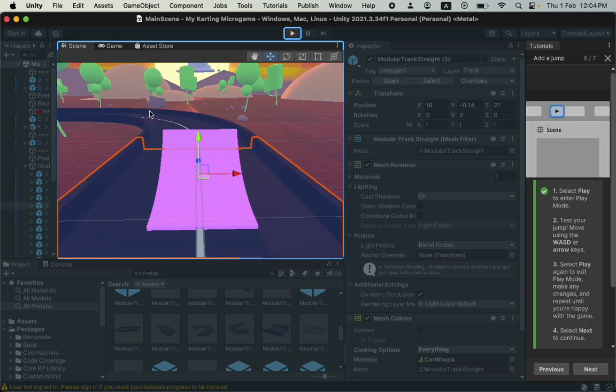Actually, that is not correct. The scene will be wherever it is. Your camera will rotate. Imagine your camera is placed on a sphere, and you want your camera to move. The scene is at the center, your camera is on the sphere. Now you want the camera to move. In that case, you hold Alt or Option key and click the left mouse button and move around.